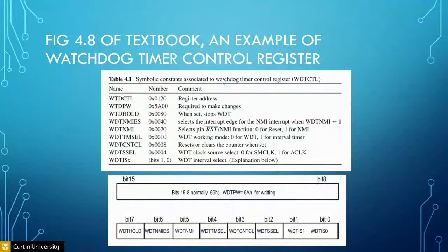Watchdog timer. The watchdog timer is basically a word, which means a higher byte and a lower byte. Now, a bit of quiz. Just now we went through instruction sets. By default, are they .w or .b? By default they are .b. So if you move or do any instruction, if you don't define it as .w, it will treat it as a byte. It only affects the lower byte.